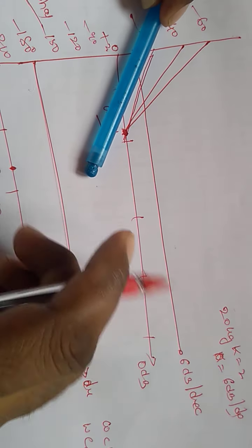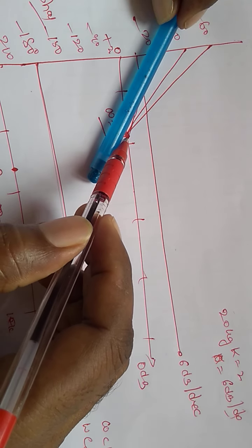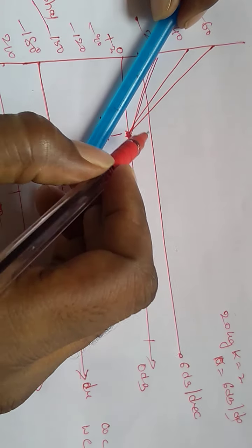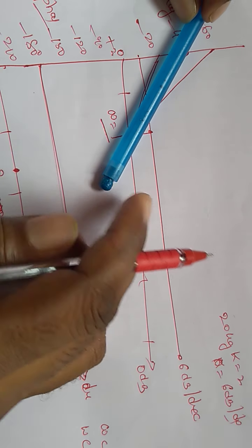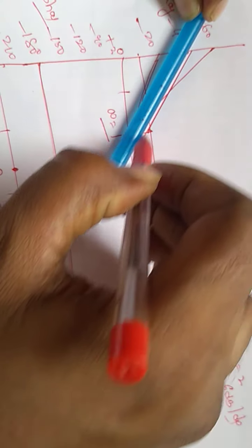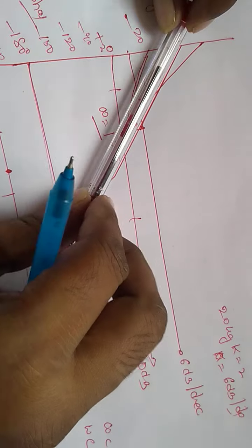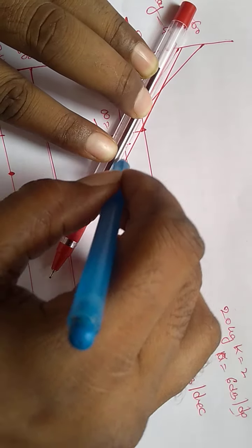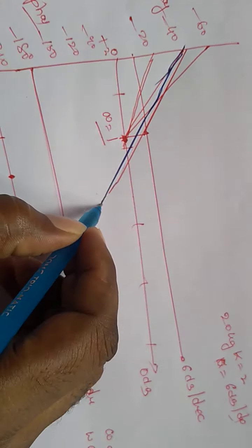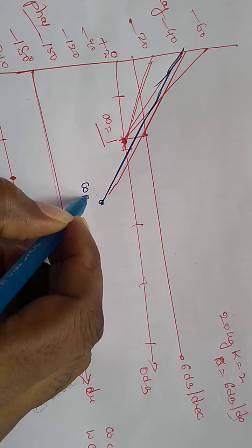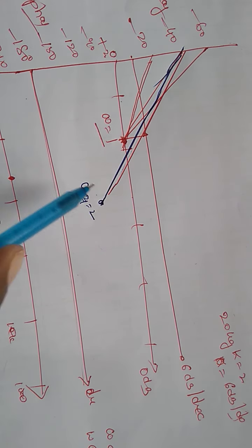20 dB per decade. So we will draw the slope line which is parallel to 20 dB, and that slope line crosses a point of 6 dB, that is the magnitude point, or else we can draw like this. Draw the slope line which meets the first corner frequency, that is omega is equal to 2. Clear? So I will explain in the graph, after you look at the graph.